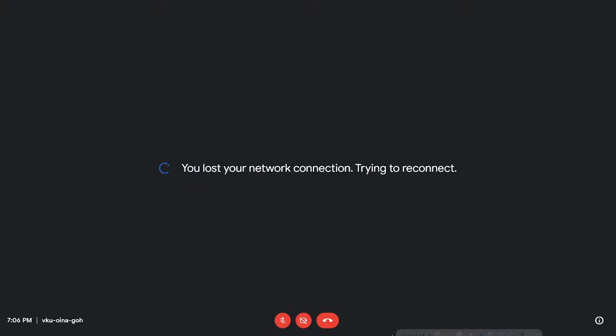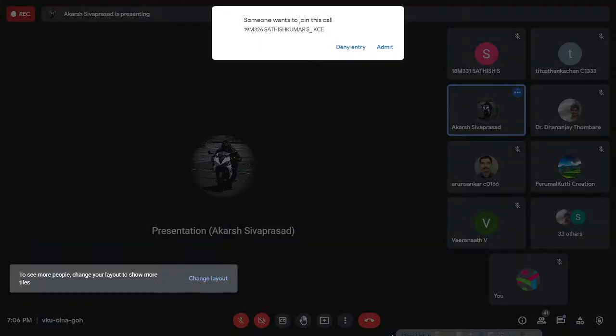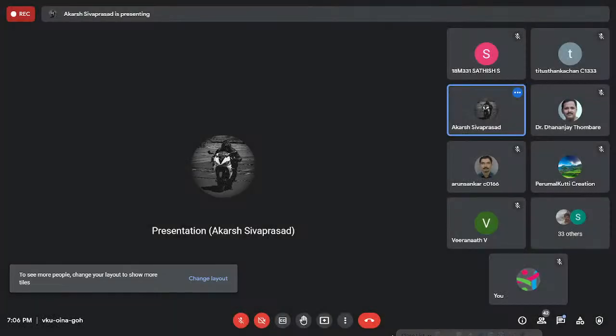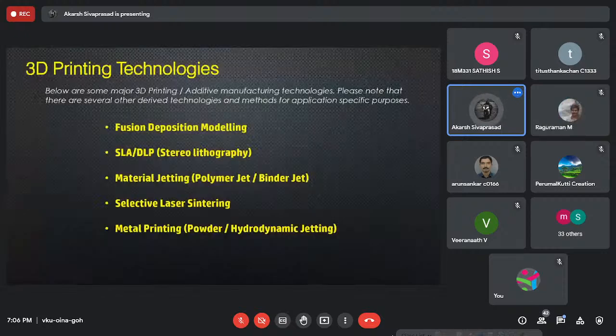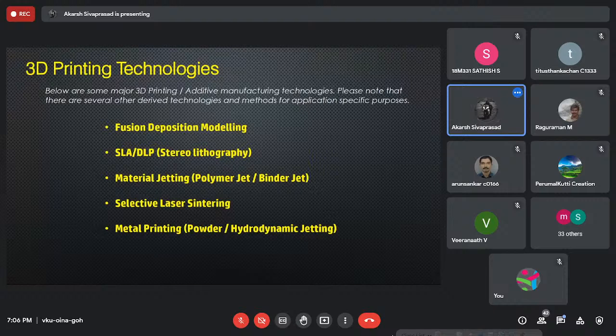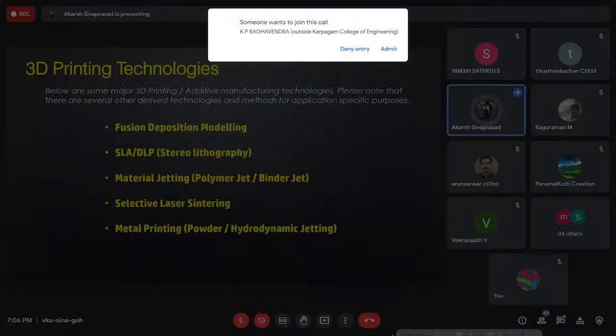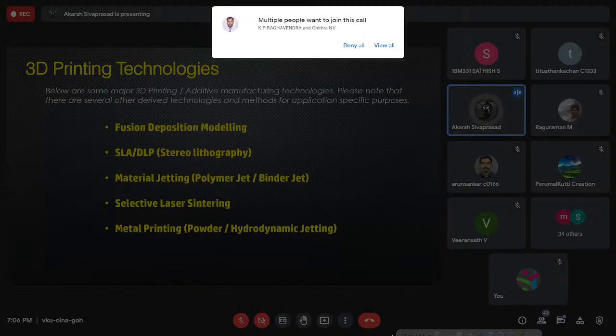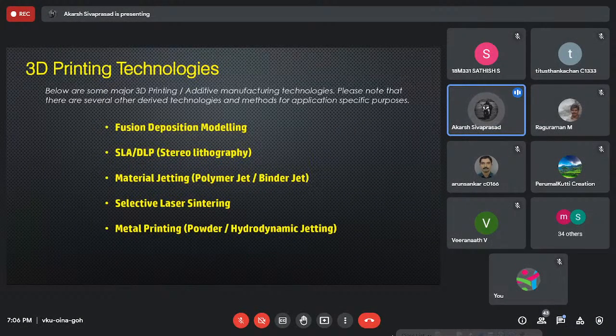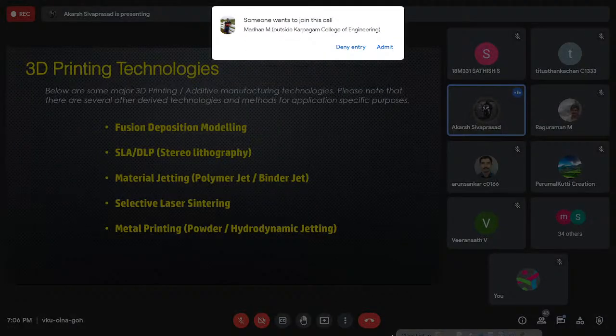And the fourth one, a little more industrial grade, is selective laser sintering. What that does is you have a big chamber of powder, usually plastics like nylon, but there are metal powders involved too. You have a super high powered laser that rasters around the block where the powder is being held, and that is done layer by layer to end up getting a 3D object.